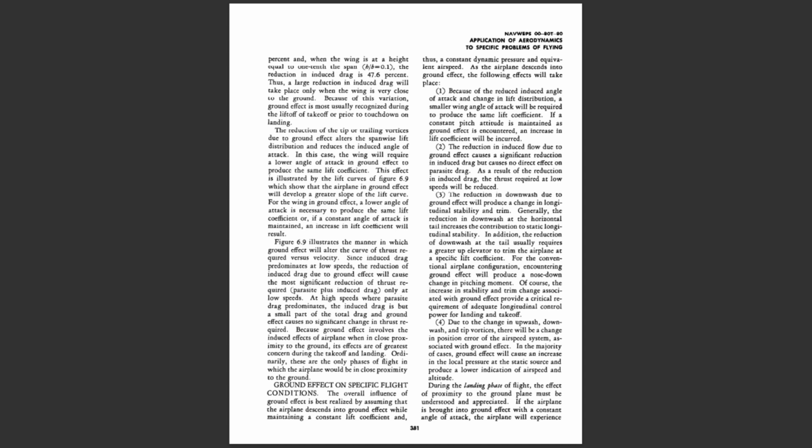1. Because of the reduced induced angle of attack and change in lift distribution, a smaller wing angle of attack will be required to produce the same lift coefficient. If a constant pitch attitude is maintained as ground effect is encountered, an increase in lift coefficient will be incurred.